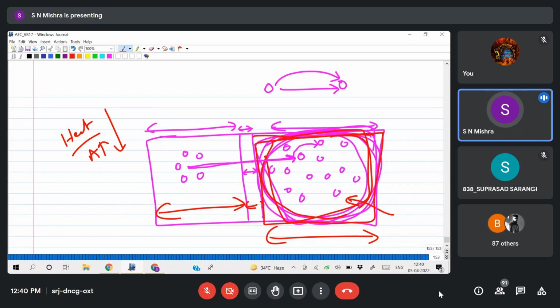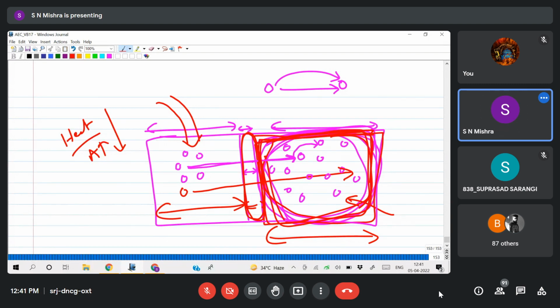Okay, so two things are done here. So the main objective is to transfer the holes from emitter to collector. To maintain that, emitter is heavily doped, and to minimize the recombination in the base region, it is thin as well as lightly doped, and to maintain lower heat or energy, the collector is lightly doped as well as wider in area. So this is the constructional view, and when the transistor is made, these things should be taken care of. Understood?